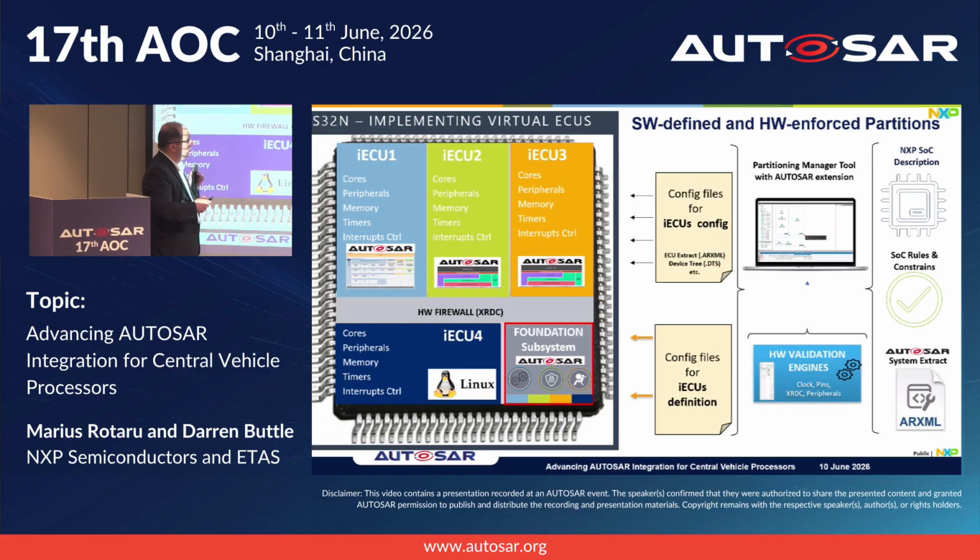In addition, the tool generates the configuration for each ECU. For example, for AutoSAR-based virtual ECUs, it generates the ECU extract, which is XML format. For Linux, it generates the device tree configuration. In such a way, each integrated ECU sees its own peripherals without seeing all the other resources.